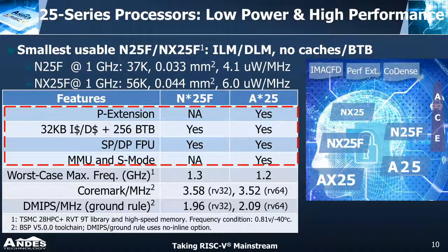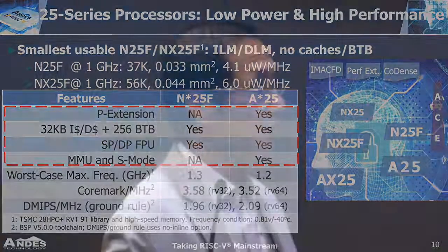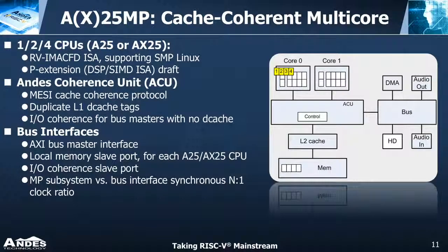So there are some details. One big advantage is that we use the RISC-V defined general purpose register as the register for this DSP. So there are no additional registers, which saves the logic and size of the core. And it supports various SIMD features like saturation, rounding, fixed point, and integer data types, SIMD instructions, and more complex DSP instructions.